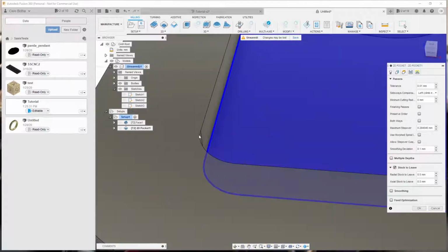Alright, so what it just means is when the cutter comes around this corner, it's going to make positions along this corner for the cutter to move on. And if those positions are too far apart, the corner might end up looking like a bunch of flat sections instead of a nice curvature. So this is the distance between the stops of the cutter as it makes its way around that corner. The tighter this is, the more like an actual arc it's going to look. Alright, so when I'm doing cutting, I like to bring that down to 1 micron.